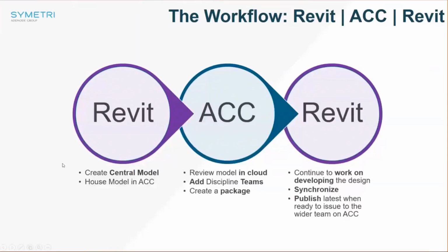Okay, so Revit to Revit then, using ACC as the cloud management solution for us here. Within Revit, we can create a central model that houses all of that data within the cloud, within ACC. In ACC, we can review the models, we can add discipline teams, or we can create packages, similar to what we've seen from the civil perspective.